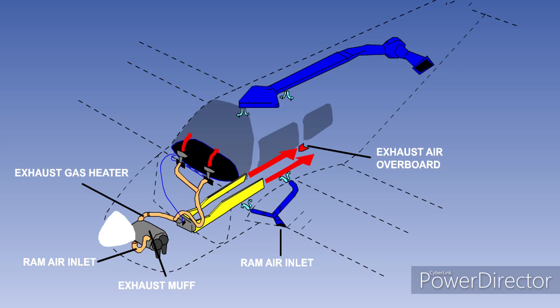This type of heater requires regular inspections to ensure that toxic exhaust gases do not enter the manned areas. Some aircraft have a blower which can be used on the ground to blow fresh air into the cabin, giving some cooling on hot days.